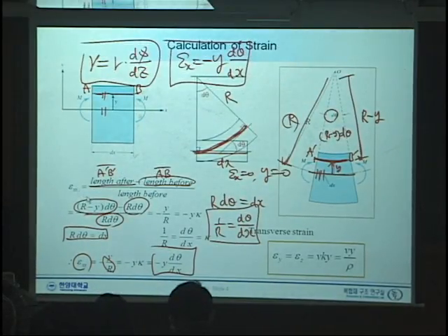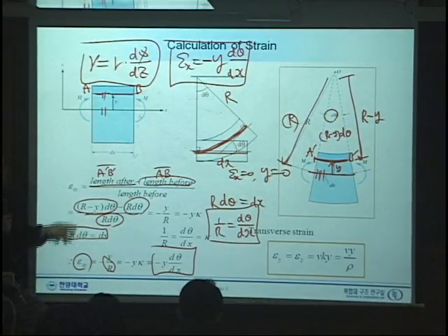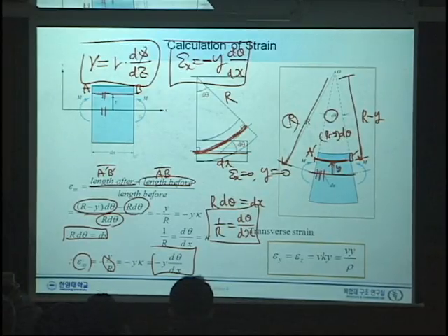And by the definition of x directional strain, x direction means along these directions, the x directional strain is given in terms of the curvature. Curvature is again defined through the radius r of this curvature, and this position is the neutral axis, which we do not know yet, and any position is defined as y.